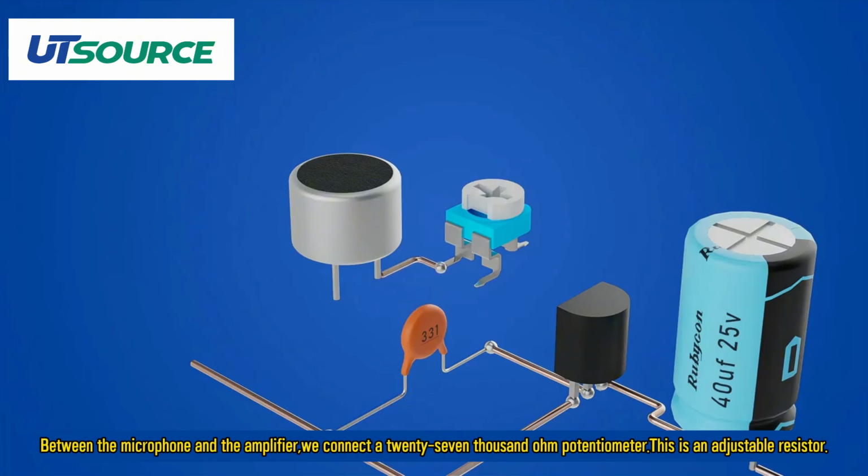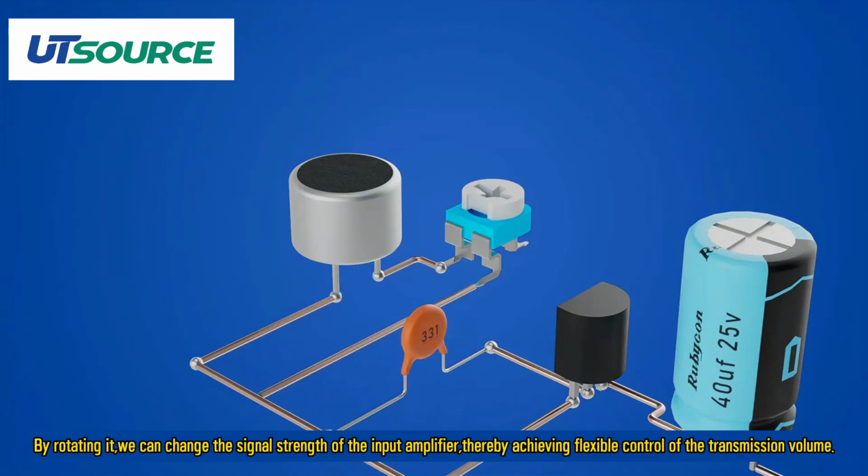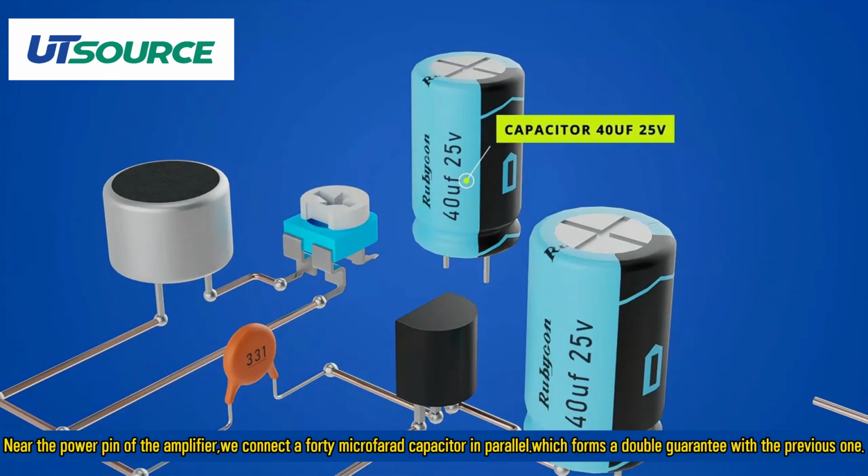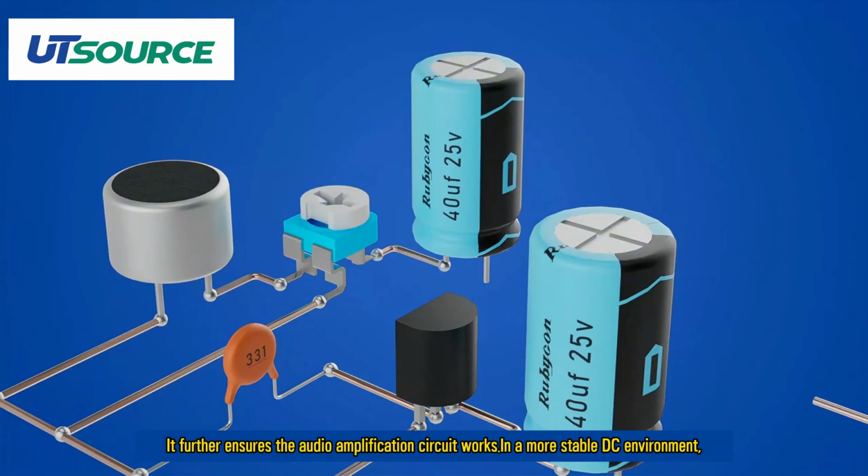Between the microphone and the amplifier, we connect a 27,000 ohm potentiometer. This is an adjustable resistor. By rotating it, we can change the signal strength of the input amplifier, thereby achieving flexible control of the transmission volume. Near the power pin of the amplifier, we connect a 40 microfarad capacitor in parallel, which forms a double guarantee with the previous one. It further ensures the audio amplification circuit works